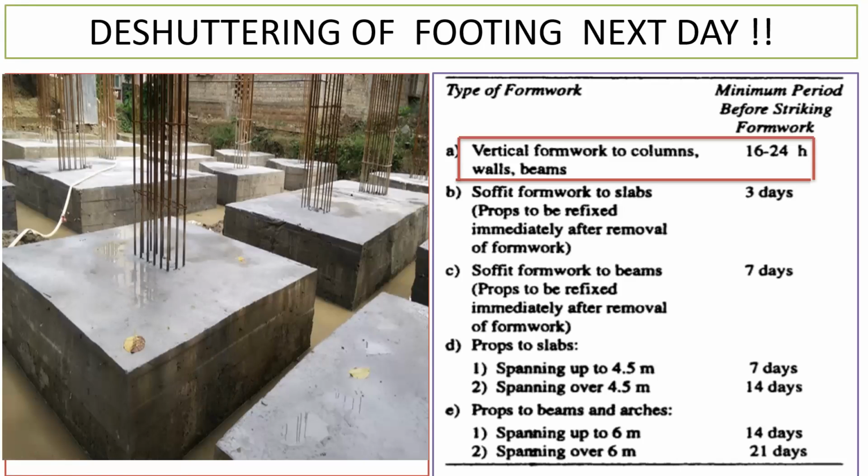If you are taking 1 m³ of the concrete, this much amount of water has to be poured. So once you pour the water and do the casting of the footing, it's not that suddenly the next day all the water is utilized by this particular cement. So it will take day by day, it's going to utilize the water that is there inside the concrete, and then it's going to give the strength.